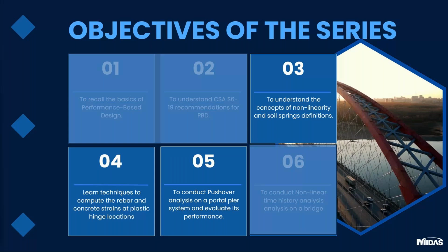So first, to understand the concepts of nonlinearity and the soil spring definitions. Second, to learn the techniques to compute the rebar and the concrete strains for the plastic hinge locations. And third, to conduct pushover analysis on a portal pier system and to evaluate the performances.